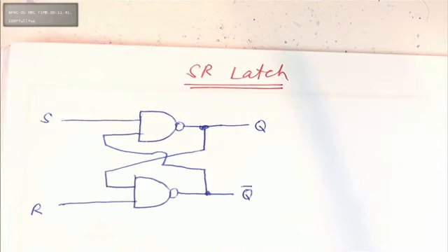These sequential circuits, the main point is this: they have memory. If you take your decoder circuit or encoder circuit, or the security light circuit which we did in our midterm exam, the solution I showed you on Thursday last week, or the mux circuit you did in your lab last week, any of the combinational circuits, the moment you change your input, the output changes. Now, sequential circuits have memory. That's the key part. Just remember that.